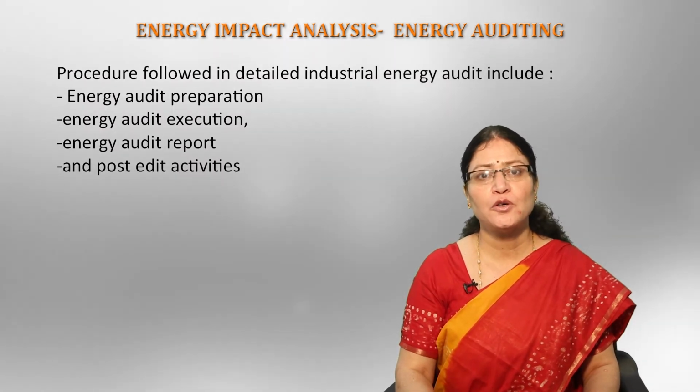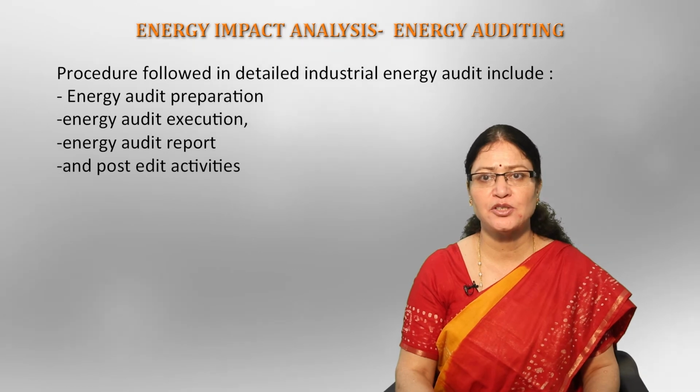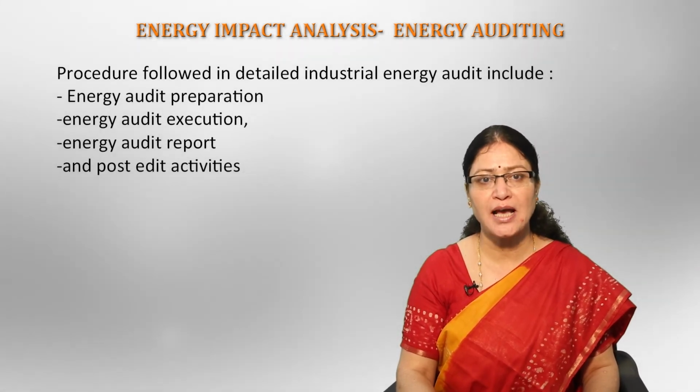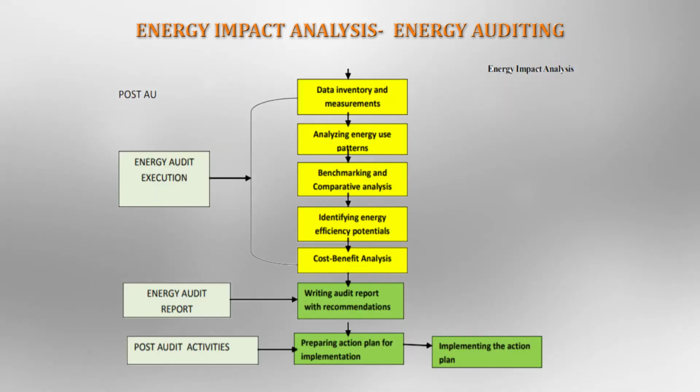The procedure followed in a detailed industrial energy audit includes energy audit preparation, energy audit execution, energy audit reports, and post-audit activities. The energy audit preparation includes audit criteria, scope of audit, selection of audit teams, audit plan, preparation of checklist, initial walkthrough, collecting energy bills, and preliminary analysis.